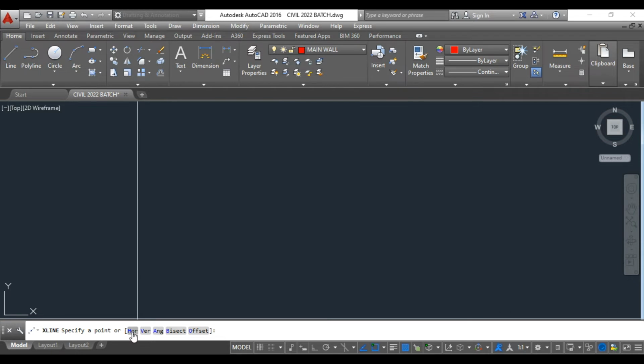If I want only horizontal axis, then I need to hit here on horizontal, or you can type capital H. Whatever you see in blue, the blue letter, indicates the shortcut of this particular method, right? See my mouse cursor, how it is shifting. So now it is pointed. When I go there, I am getting a fingertip, which means this command will work. If I take this one, I am getting a small vertical line. It is not at all going to work over here.